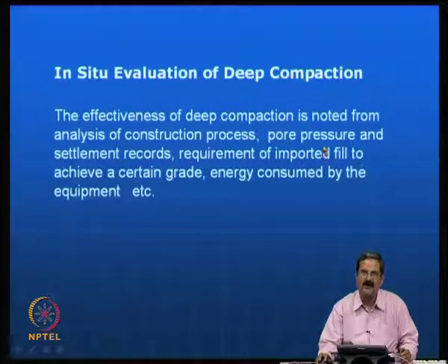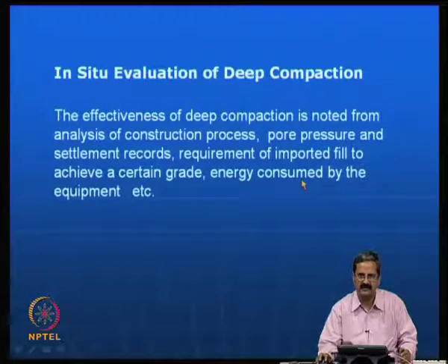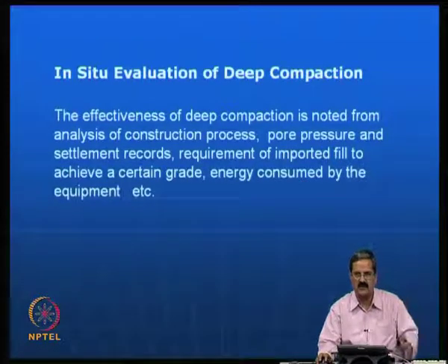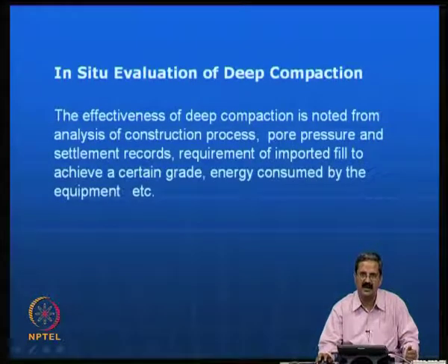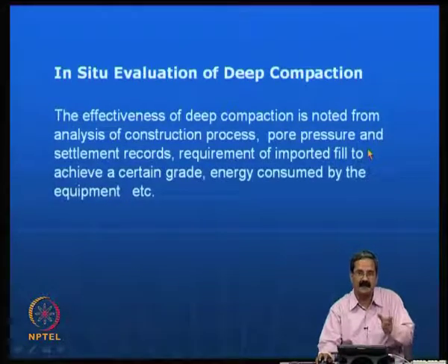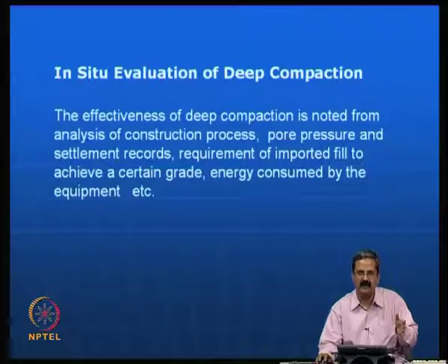As I just mentioned, in the process of dynamic compaction, the pore pressure is mobilized because the rate of loading is so high that a lot of pore pressure is generated, and the rate of dissipation of pore pressure tells you what type of soil it is. Say for example, in clays, pore pressure mobilization is very important. So, you need to decide the time lag for the next tamping.